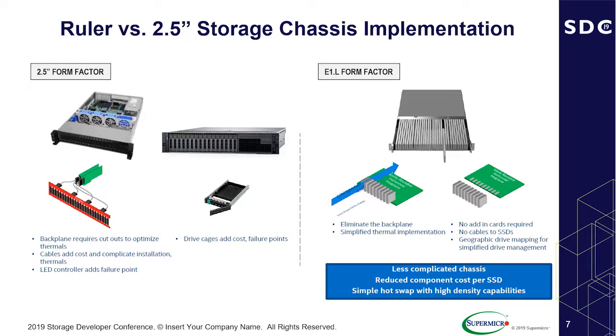There's an 18 millimeter version of this where they have fins on both sides, and of course the problem is the minute you design it for a 9.5 like this is, and like the system you see out there, you can put an 18 millimeter in the middle, but the minute you go up against a wall, well, it doesn't fit, right? So you end up wasting a lot of space. You have to redesign the whole system to shift everything in order to fit an 18 millimeter drive kind of thing. So that's a variant of this, but there's the 25 millimeter, basically huge heat sink that sticks out here.